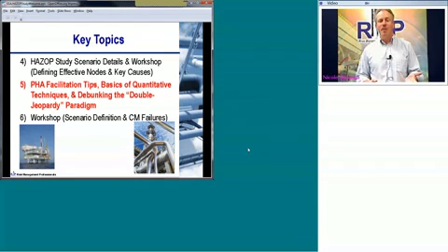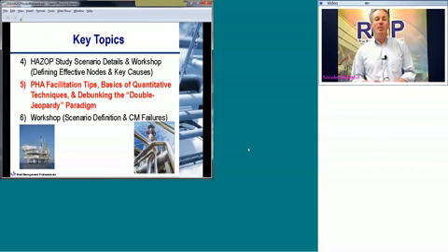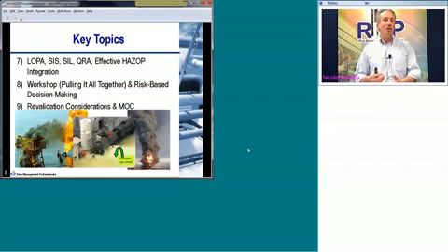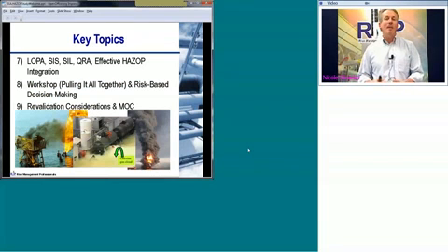The next module after this will be a workshop on scenario definition and common mode failures. Then we're going to get into some of the more detailed topics for people who have safety instrumented systems and have to do safety integrity level calculations. There's a variety of techniques. The most commonly applied one is layer of protection analysis, or LOPA. I want to talk about that and how that interfaces with HAZOP studies.